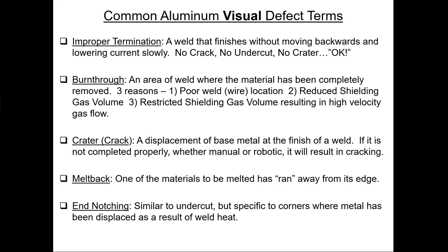This is a visual inspection. In most cases, it's a visual inspection to begin everything. In fact, all welds, it doesn't matter whether we're talking about automotive, pipes, pressure vessels, or structural, begin with a visual test. Is it in the right place? Is it the right size? Things like that. So, shall we go on?